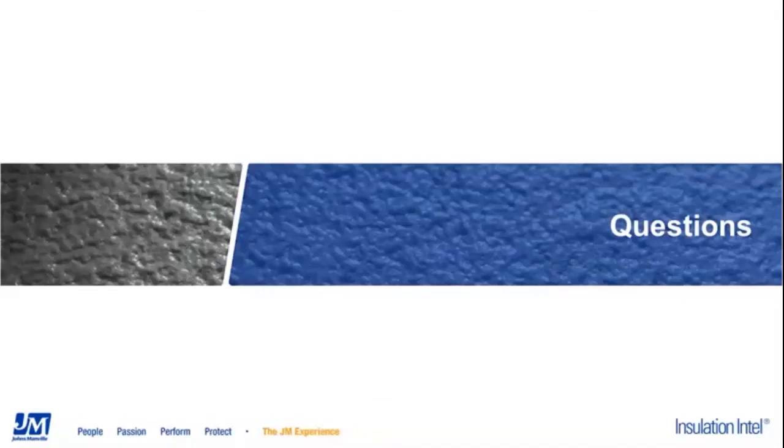Excellent, thank you. The next question is, what are the potential consequences of cross-contaminating during a changeover procedure? Okay, sure. Going back to that little recirculation kit, realize that 10-foot, 20-foot chunk of hose still has product number 1 in it. So let's make sure we're not opening up that pressure relief valve and dumping that whole line set back into product 2's drum and cross-contaminating.